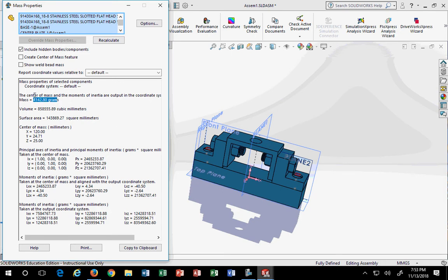So all of a sudden, it was only 800 something. Why? Because probably the only thing it was measuring was the fasteners. Because the fastener they assigned material to, because that came from another party. But my parts, the material wasn't assigned to them. Get it? So as you assign the correct materials to each part, this starts becoming more accurate.